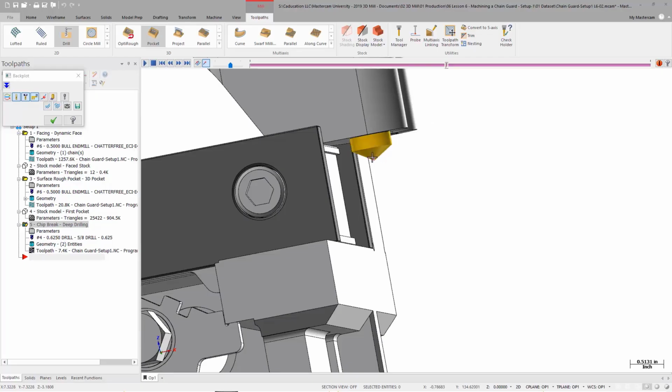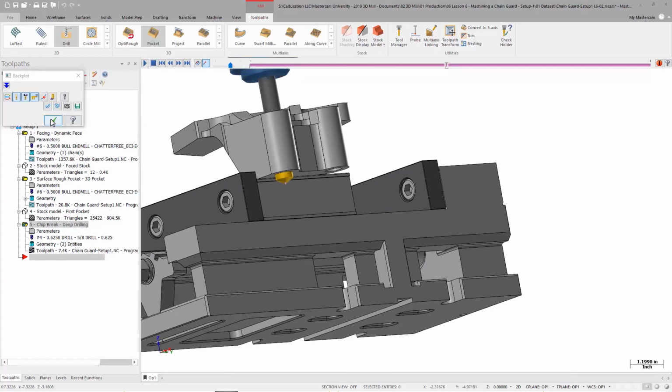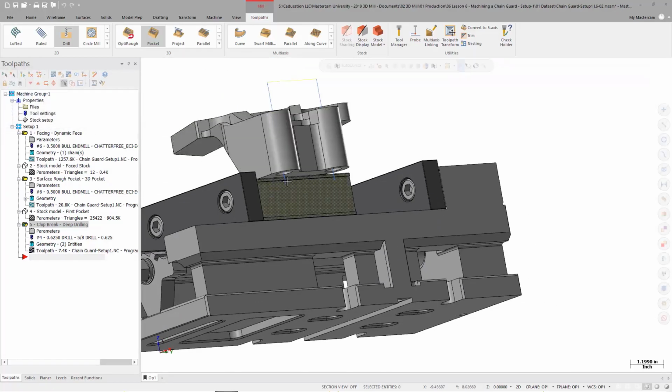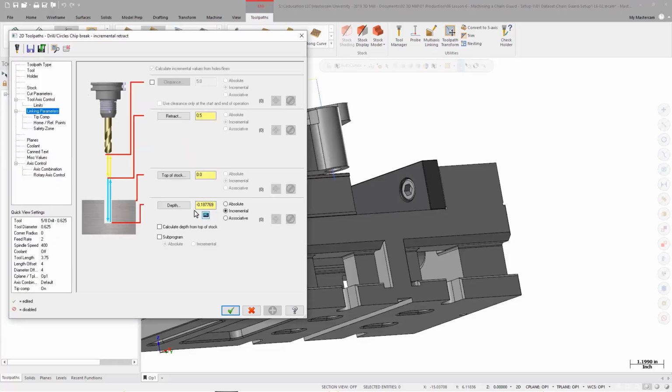So we can see here the drill bit, and more specifically the major diameter of it after the taper does extend all the way through the hole. But what if we wanted to change the distance or the position of that? We can obviously go back into the parameters, we can modify the tip compensation or the depth calculator.